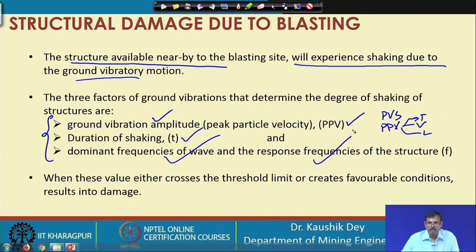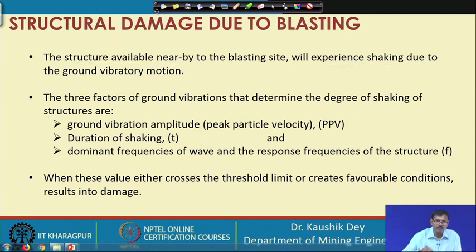That is why low frequency waves come in the earthquake, and unfortunately most of our civil structures have a response frequency which is also low, and that is why resonance occurs. That is the basic idea, and that is why the damage that occurs in an earthquake is so much of a concern.